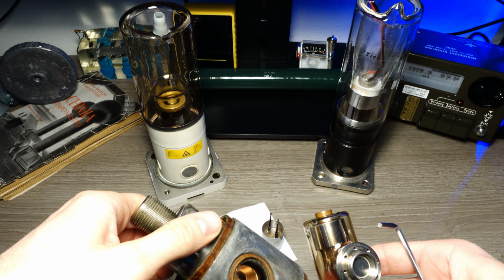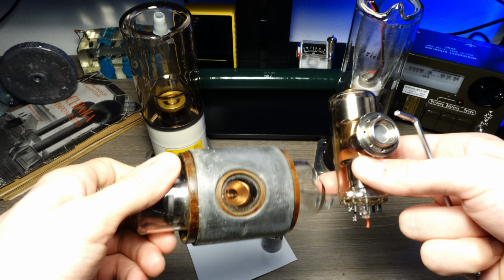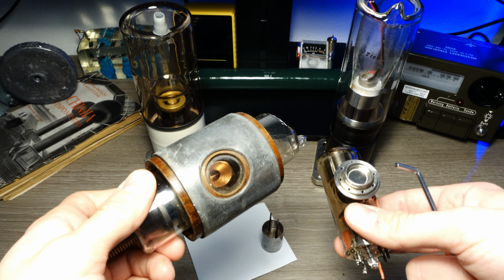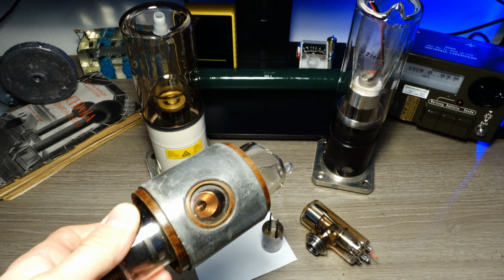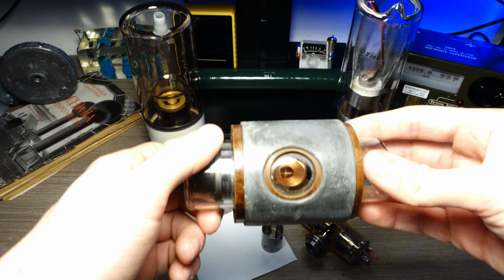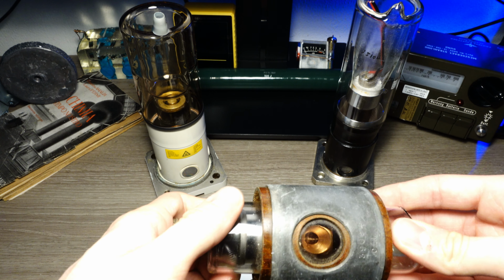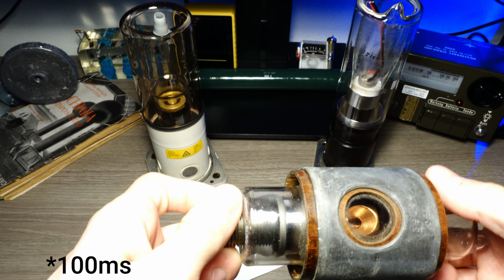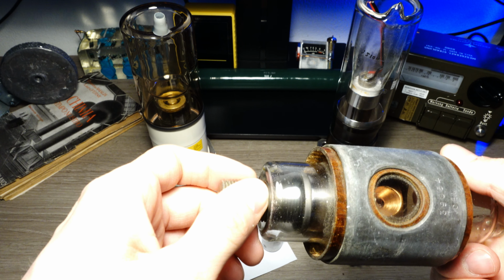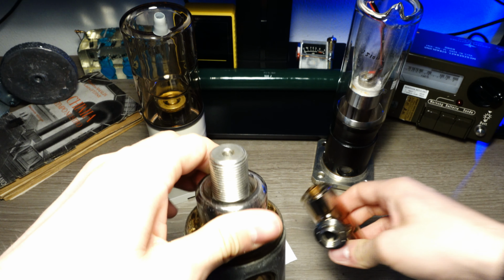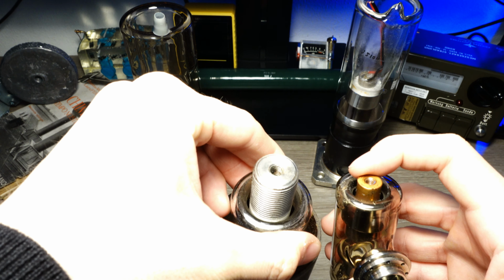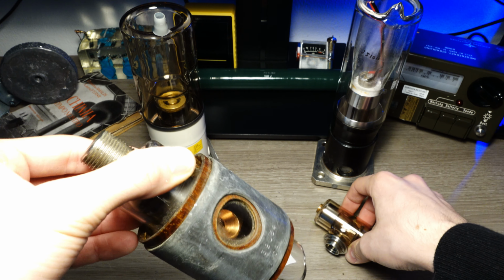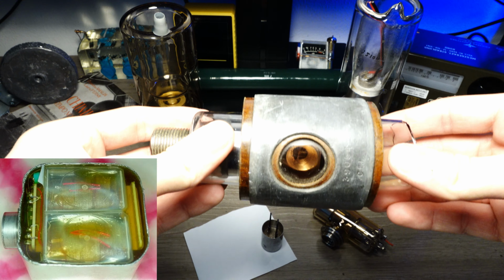So these two tubes that work in a similar way also have relatively low power consumption, because they are used in medical devices. They usually need to be operated in a pulse mode, so you send a pulse of high voltage that lasts maybe a few microseconds or even less. For this reason, the operation uses low power, and this allows the anode to be at a high voltage potential, because the power can be dissipated through the oil in which the tube is normally placed.